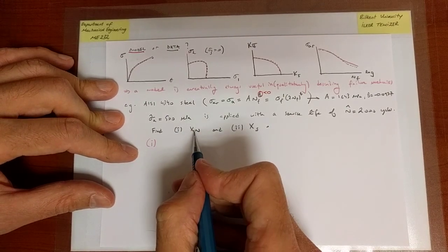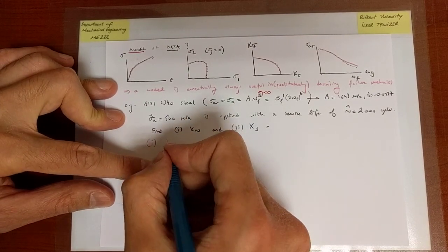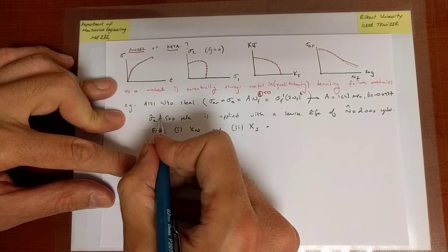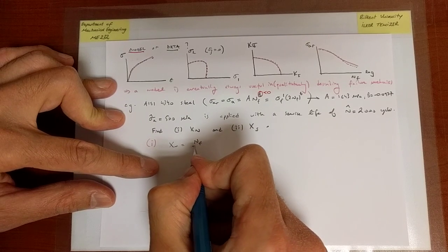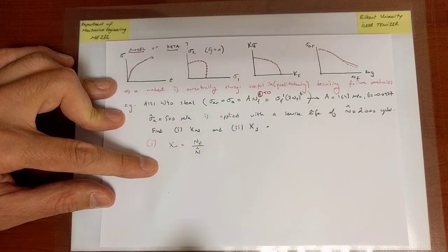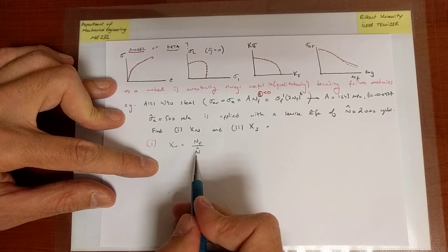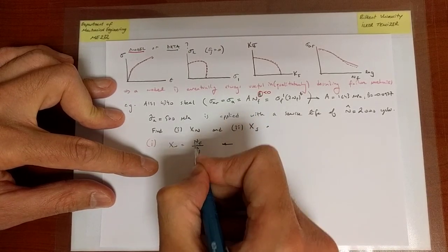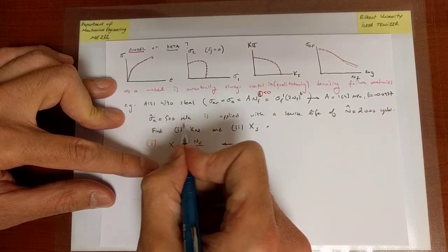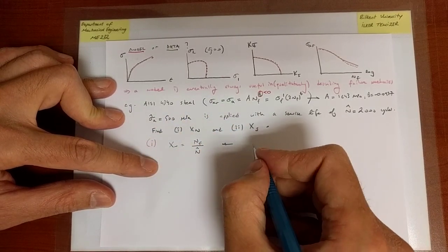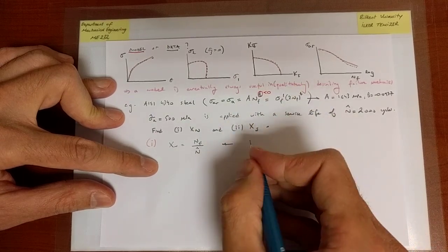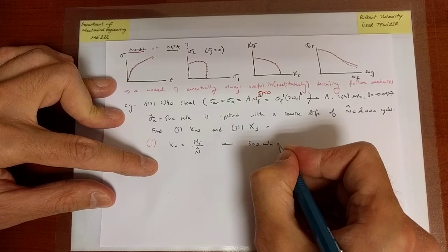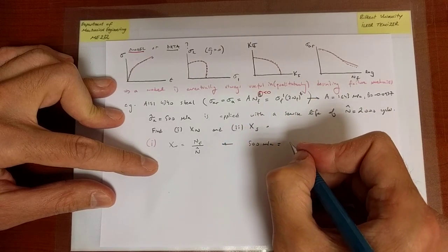Now, the way we are going to calculate safety factor on life is, remember, there is a certain number of cycles to failure under the conditions that are provided, but we don't want to cycle up to that point. We cycle up to the service life, which in this case is 2000. So what I need to do is find what NF is. Now, NF corresponds to the life for this given stress. So I'm going to make use of the Basquin equation, and I'm going to write on the left 500 MPa is equal to A and F to the power B, or